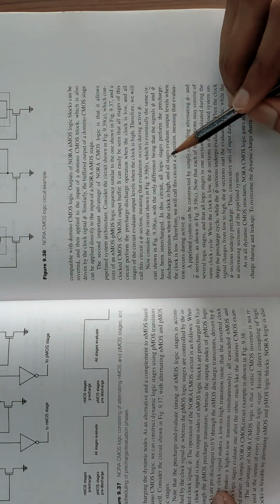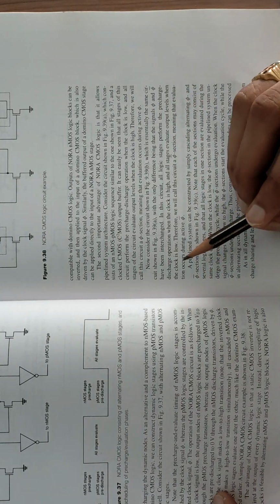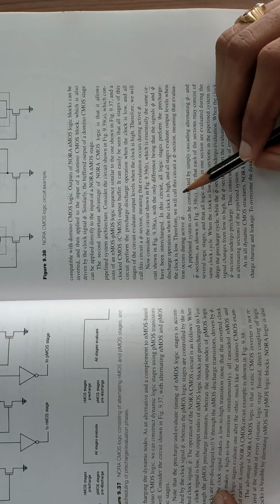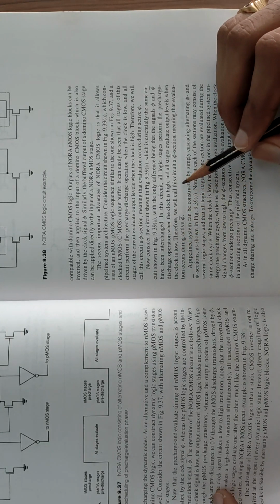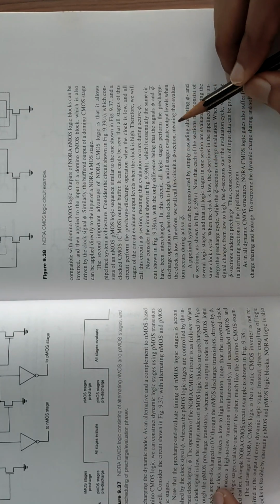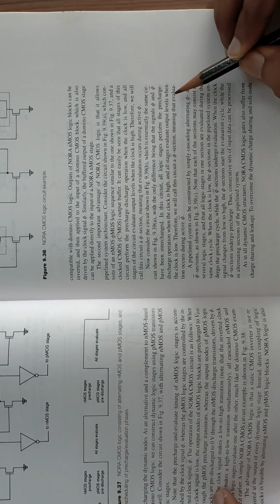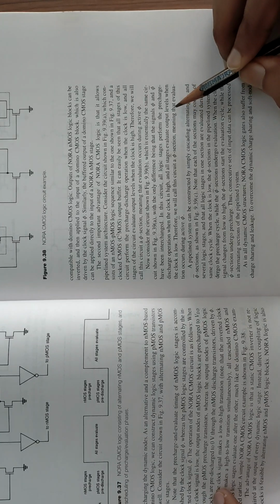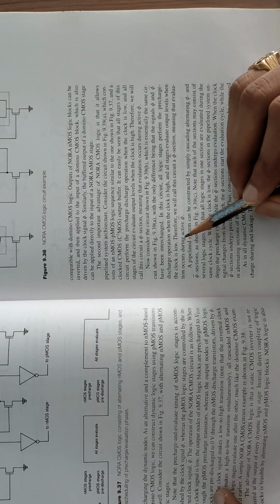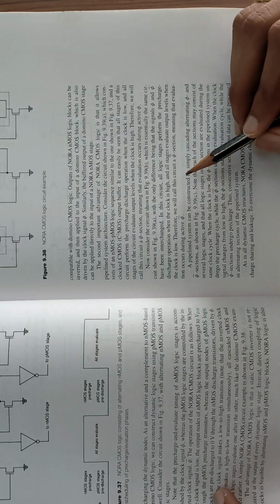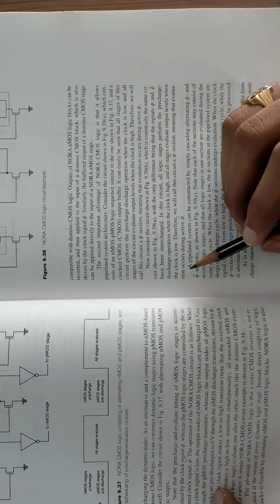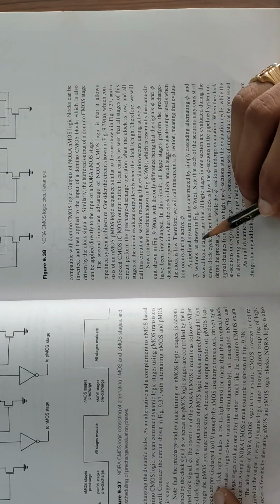In this circuit, all logic stages perform the precharge-discharge operation when the clock is high, and all the stages evaluate output levels when the clock is low. Therefore, we will call this circuit a phi dash section, meaning that evaluation occurs during active phi dash.